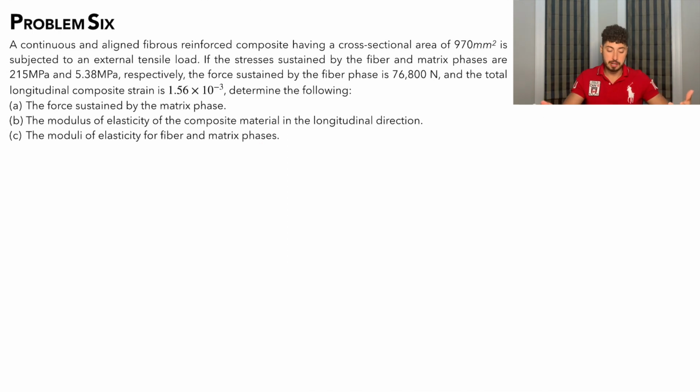So let's deal with part A first. Part A wants us to find the force sustained by the matrix phase. Upon reading the problem, we immediately notice we are not given any volume fractions of either the fiber or the matrix. So we need to find a way to find one of the two and then be able to find the force sustained by the matrix.